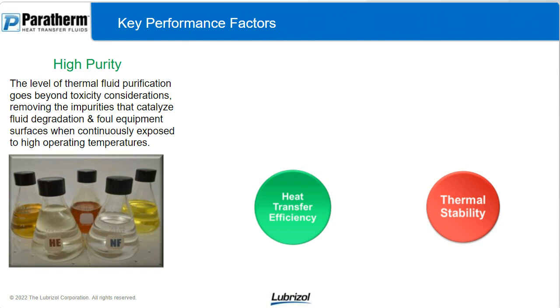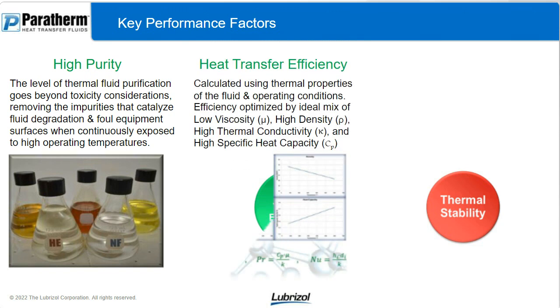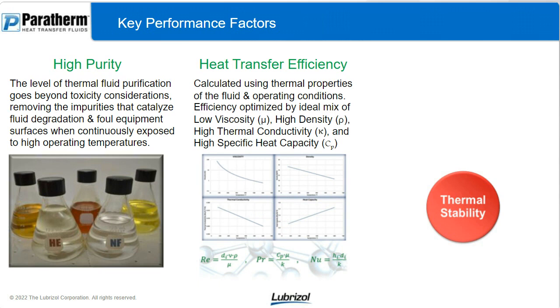High efficiency. This is calculated using thermal properties of the fluid and the operating conditions. So you can take your flow rate, your temperature set points, and your pipe sizes for any system, and then plug in the data values for the fluid.